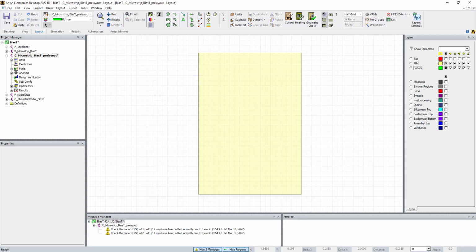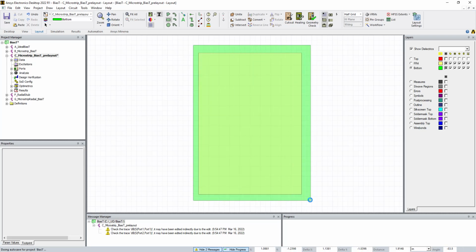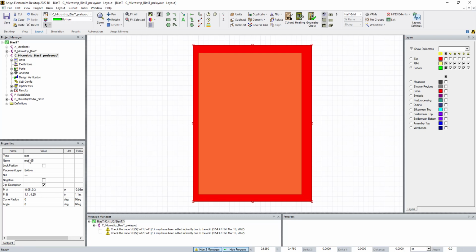What you're going to do is just grab another square and drag it. It doesn't matter what, because we're going to type everything in. So you just drag a square. You go down here and ask, where does it want to be? Well, remember, it wants to be a trace offset inside from each of these points of the dielectric, because this whole bottom layer is going to be a solid ground plane. So that means that the x-axis start is W trace offset, comma, the connector offset minus the trace offset.